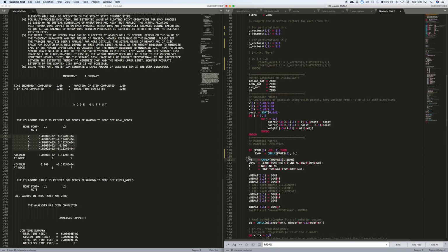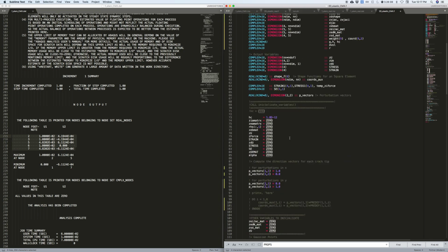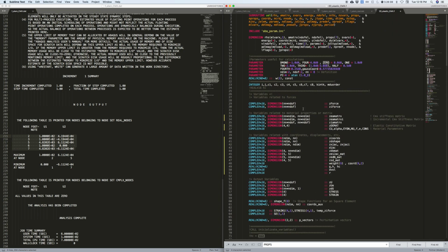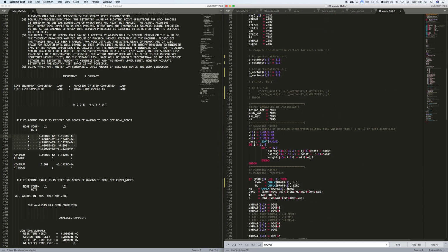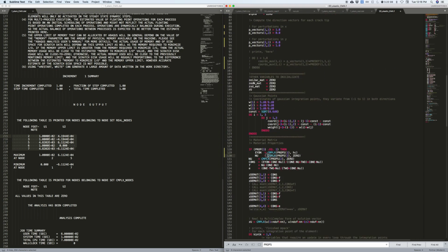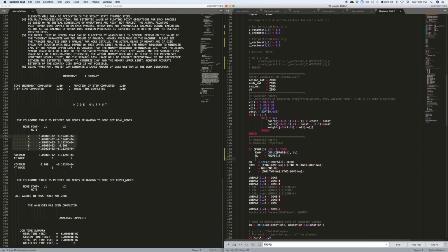Then your Poisson's ratio is not complexified. You can either do that one, just saying that in your imaginary direction you have a value of 0 that I defined here in the beginning of the analysis as 0.0 double precision 0, or you can just say, hey, it's only the property number 2. That means that it only has a real part.